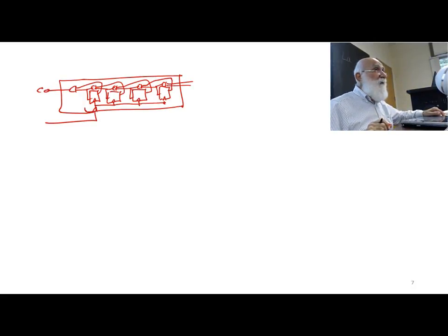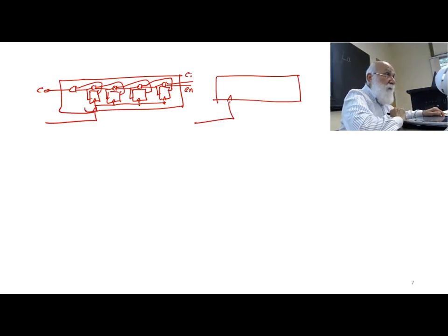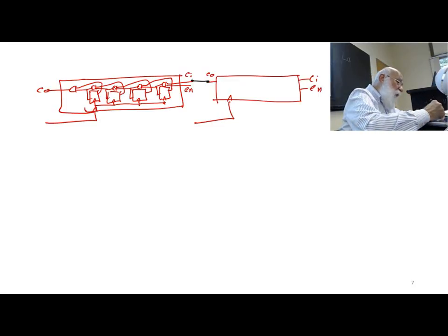Okay, this is the 4-bit up counter, and this I regard as carry in, this I regard as enable. If you decide that you want to take 2 of these and build an 8-bit counter, it has a carry in, it has an enable, it has a carry out. Connect the carry out of this to the carry in, put a 1 on the carry in of the right one,